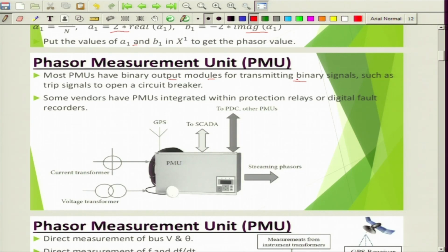The position of a circuit breaker is either 1 or 0, and likewise capacitor bank positions; some of the data would be binary. Hence, we also use MINLP, mixed integer nonlinear programming, based approach for optimization, because the power system is nonlinear and consists of integers as well.